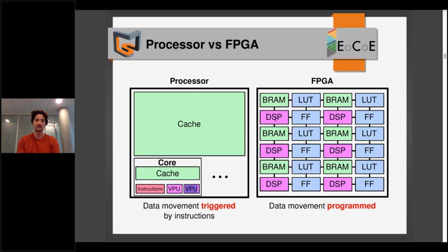So that's a very versatile piece of hardware. You have BRAMs, which are little pieces of memory where you can store data. You have LUTs, lookup tables that implement some logic when you need it, and flip-flops. That's a piece of silicon that is able to store 1 bit of information. You can aggregate these bits to form registers typically, and do logic with lookup tables.